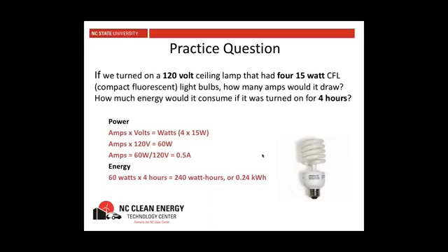And a lot of customers don't particularly like to talk about energy efficiency, but I do think it's a valuable conversation to have with people. If people have got 60-watt light bulbs, maybe it's time to replace those with LEDs or CFLs. Well, I would just say it is time to replace those with CFLs or LEDs. It does make a big difference. It's not the major power draw in most people's houses. The thing that uses the most energy in most people's houses is the HVAC, refrigerator, and the water heater.